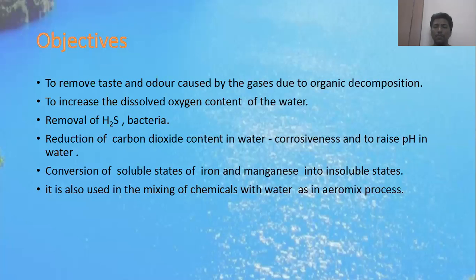Therefore, if the corrosive content becomes too high, what happens? It may impact the treatment plant where pipelines or networks are used, and again when it goes to distribution systems, there also it impacts in the same way. That means it imparts corrosiveness to the water pipelines. From there, the corrosivity will lead to leakages or bursting of the pipe. This content should not persist. We do this so that it does not happen.